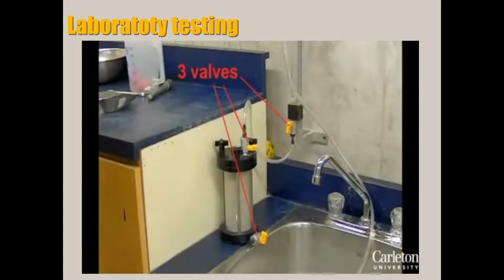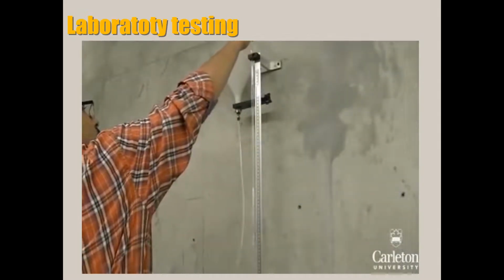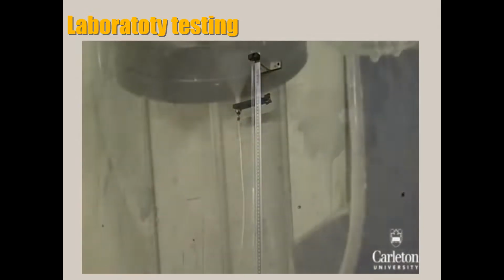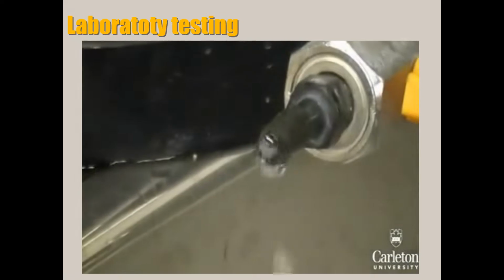There are 3 valves in the system. Make sure they are all open. Start adding water to the top of the standpipe. A larger funnel can help you do this more easily. As you can see here, water will start moving into the test cylinder and saturating the sample. When water starts coming out of the nozzle at the bottom, as you can see here, we can proceed.